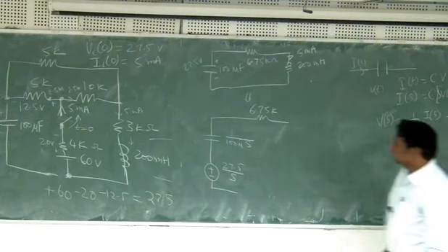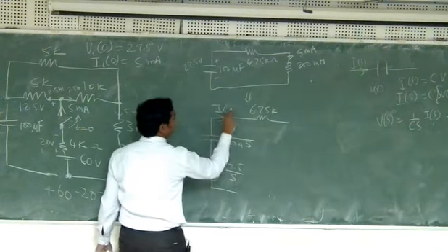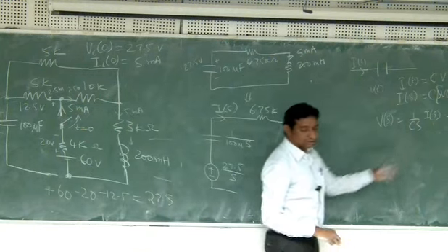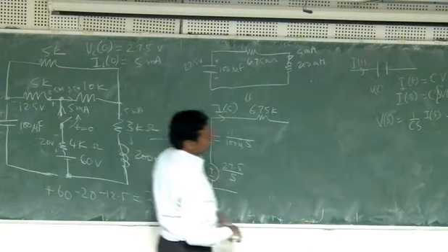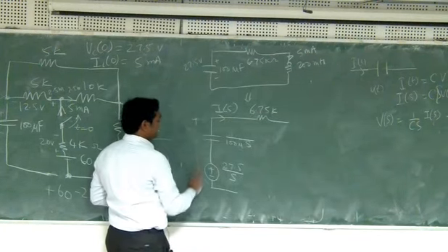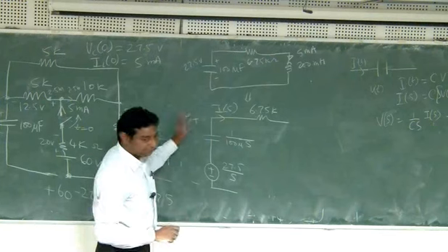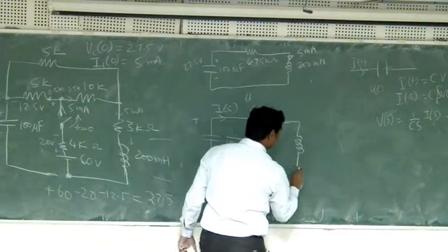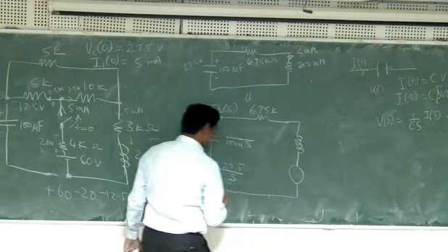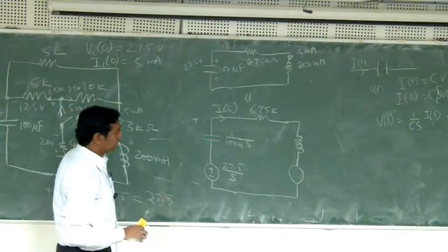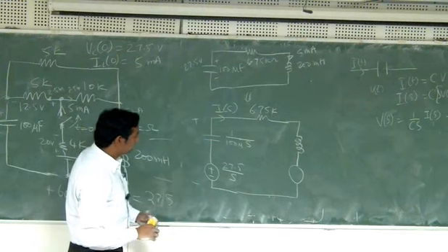Okay. So if there is a current I of S flowing, this I of S multiplied by this is the first term, this is some voltage, and V0 by S is the other voltage. These two voltages together will add up to my initial voltage of the capacitor. Okay. So the same thing happens here with the inductor, and then I can put a voltage source. Or if I am interested, I can actually put a parallel current source also. We will go with the voltage source.